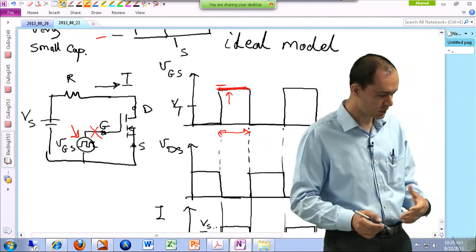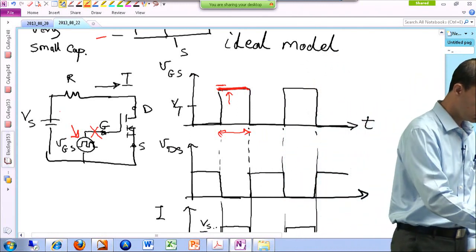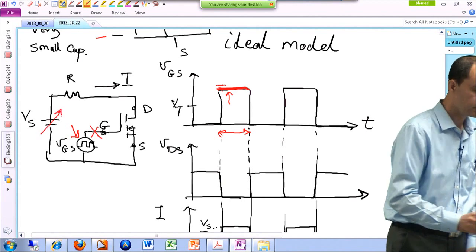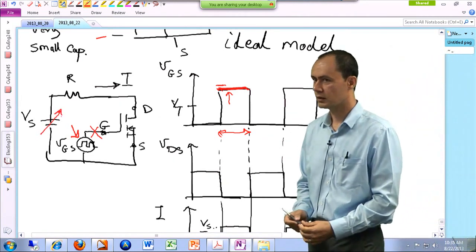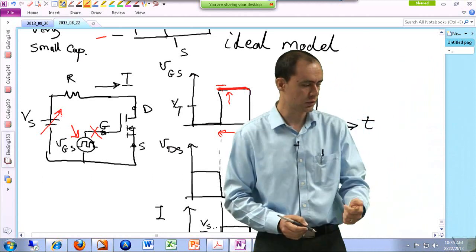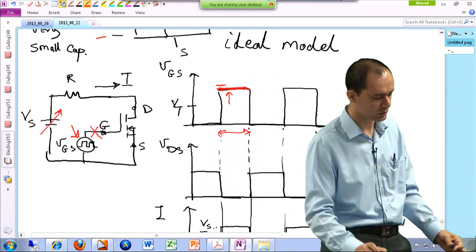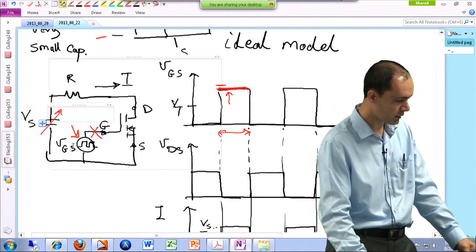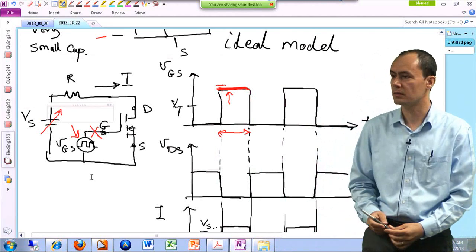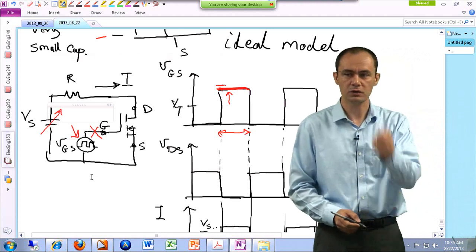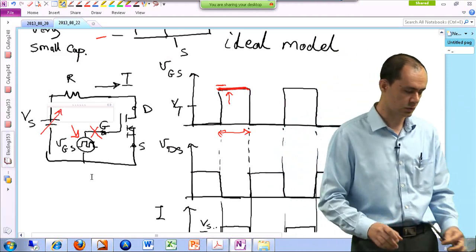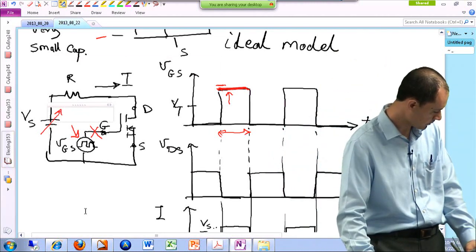So please remember, dial down this supply voltage over here first. When the supply voltage is down to zero, then you can disconnect or turn off the signal generator that is connected to your gate. A lot of times students blow up a MOSFET or kill it, because they suddenly turn off their gate-to-source signal generator.